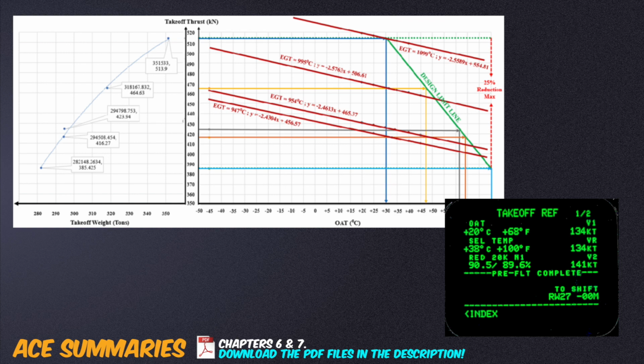The following is an extract from Wikipedia. The runway length required for an aircraft to take off is calculated for each flight. Depending on the aircraft weight, the air temperature, and the wind speed, this length may be shorter than the available runway length. The crew can calculate the low-power engine setting, where takeoff will use a larger portion of the runway. Lower power settings reduce noise, engine wear, and maintenance costs. This technique is based on air temperature rather than the percentage of engine power to be used, because it is easy for the crew to look up and calculate the highest air temperature at which any particular takeoff can be performed.